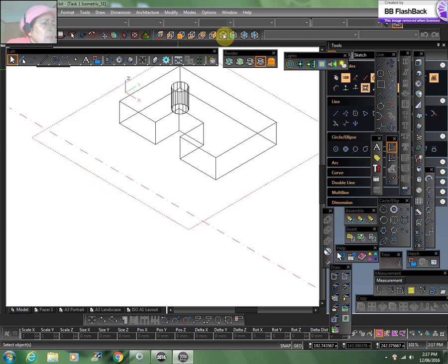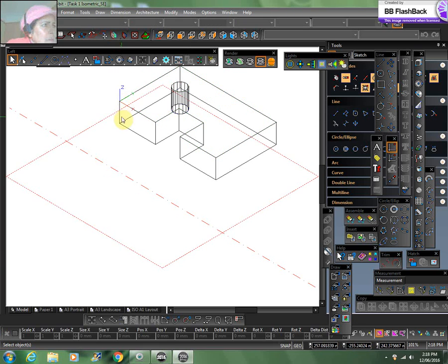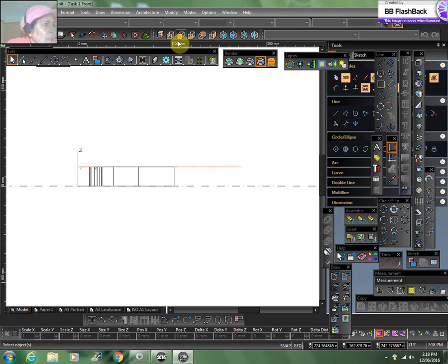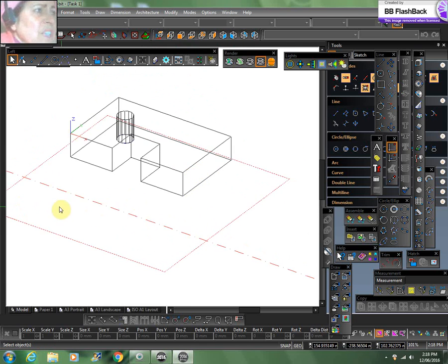So we go here and we go work plane by facet, we go further, we put it on here. Then if we do this one, it is exactly on this corner. It's sitting on this corner. So we go again to isometric view to see it better. We shifted this work plane that we created, the 2D object, to the top surface, and now by doing this we have to shift the circle that was at the bottom to the top as well.